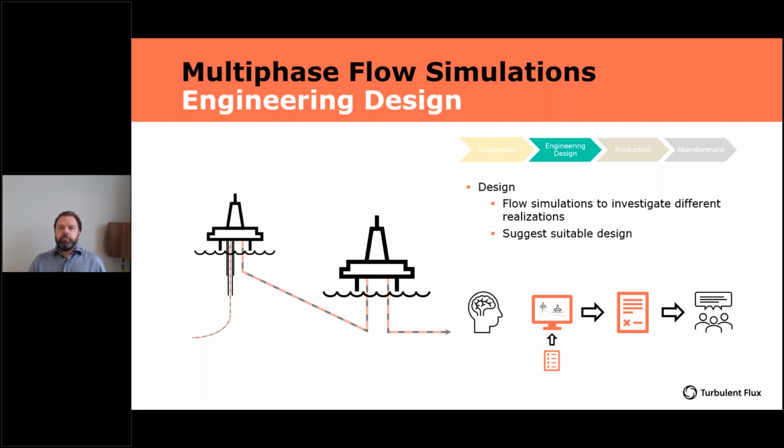And it has been claimed to be the technology that really facilitated long distance transport of multi-phase flow. Before that, you were producing more locally, you were separating your phases. Long distance transport was predominantly through single phase pipelines. But with this, you could then go longer, further, deeper, and it has been then a driving force toward, for example, subsea developments.